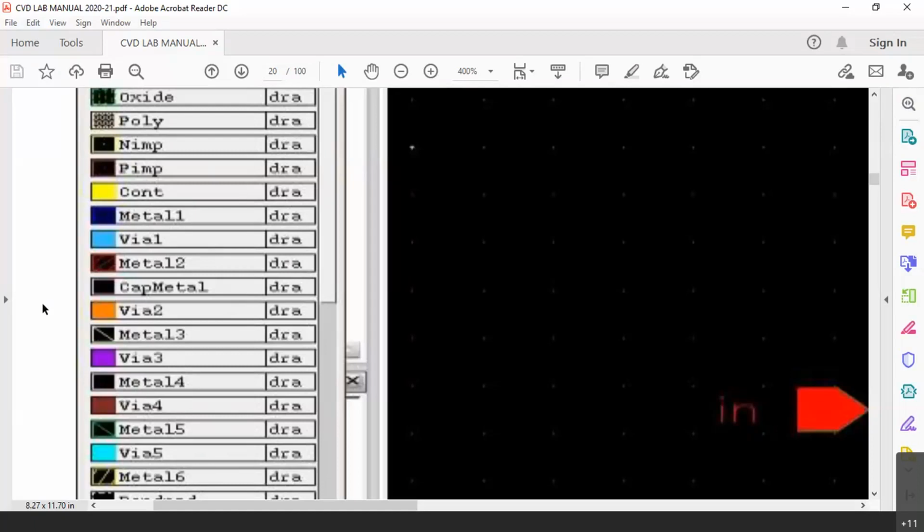We will have to use via. This via is like that particular lift. Now this metal is made up of copper, whereas via is made up of tungsten. The reason is via has to be much stronger to have a physical support between two layers. Again, remember, we are dealing with nanometer dimensions.